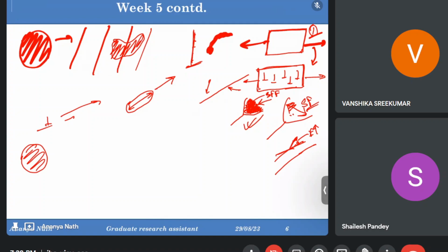To increase the hardness, we do quenching, because quenching is like heating a particular material above the recrystallization temperature, and then we cool down the material very rapidly by dipping the material in oil or water. But normalizing and annealing are somewhat different from quenching. In annealing and normalizing, we get back the ductility to some extent. So we increase the ductility, or in other words, we decrease the hardness.